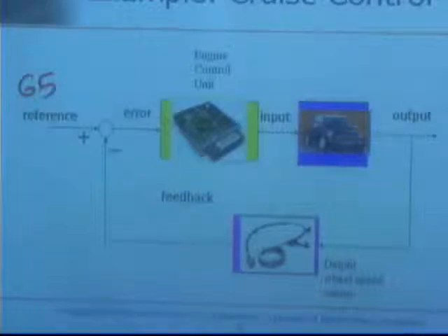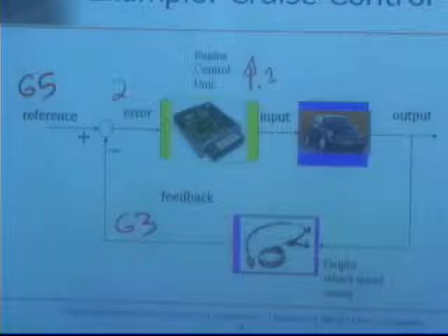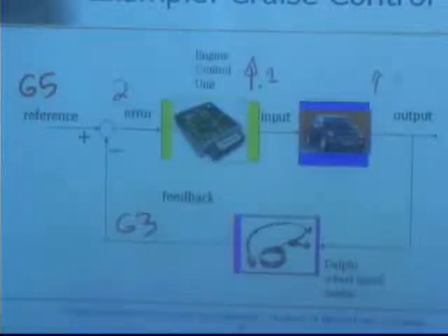That's an additional thing I haven't talked about too much. I'm going to gloss over this. But if this is coming in here at 63, based on the velocity, my speed signal picks up that I'm doing 63 miles an hour. I've got a 2 mile an hour difference. What the engine control unit says is increase my throttle angle by 0.1 degrees. So I go ahead and open up my throttle angle a little bit more, let more air into the intake manifold. I get a bigger boom per combustion, right? And so I end up increasing my speed a little bit by 0.5 degrees.